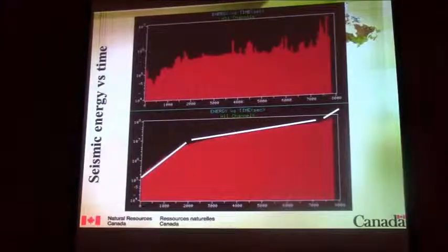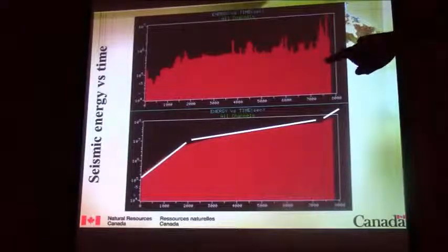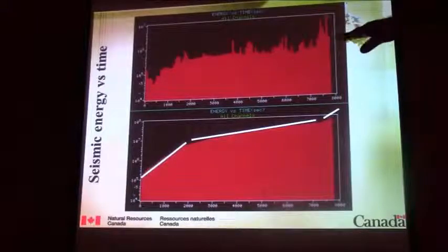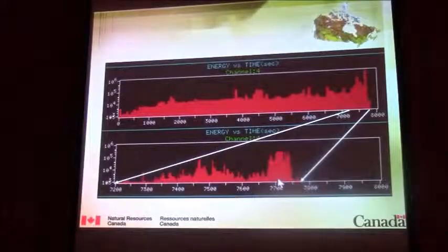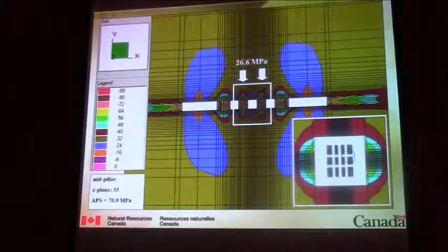So here's some of the acoustic emissions that we were recording. You could see as our time went by, over 8,000 seconds over here, we could see the initial ramp, then a more stable ramp when we slowed the loading, and at the end, the acceleration as we headed towards failure.